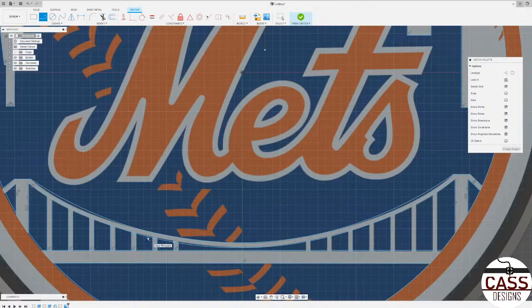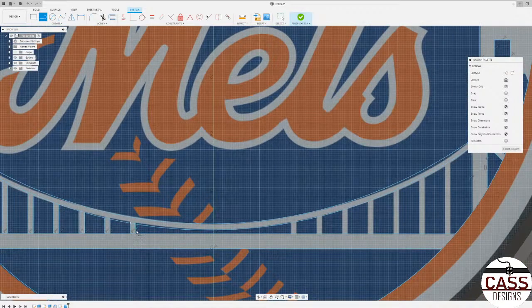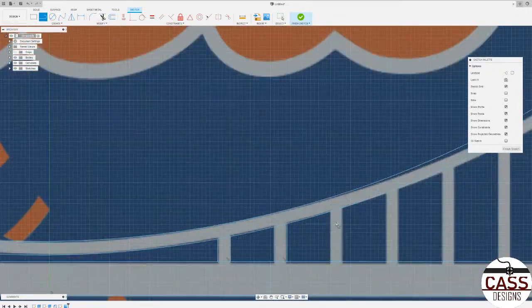And another thing here, actually, this palette, never mind. It's going to do the mirror tool, but sometimes, so see how right here we have these lines that are attached to this arc that we created. I was thinking about mirroring it about this green line here. The issue with that is I don't know if these would line up to this arc perfectly, and that would cause some issues, so I'm just going to take the extra minute or two to draw this out without screwing something up.